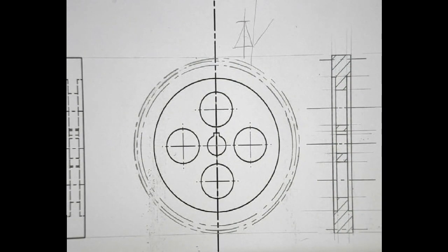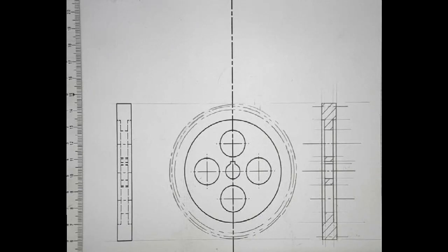Okay, the next part of this drawing that needs to be completed is representation of the pinion itself, where we'll basically be drawing this body to half scale above our gear with the specified distance between gear centers. The distance between centers that we calculated in the previous example was 126.9.